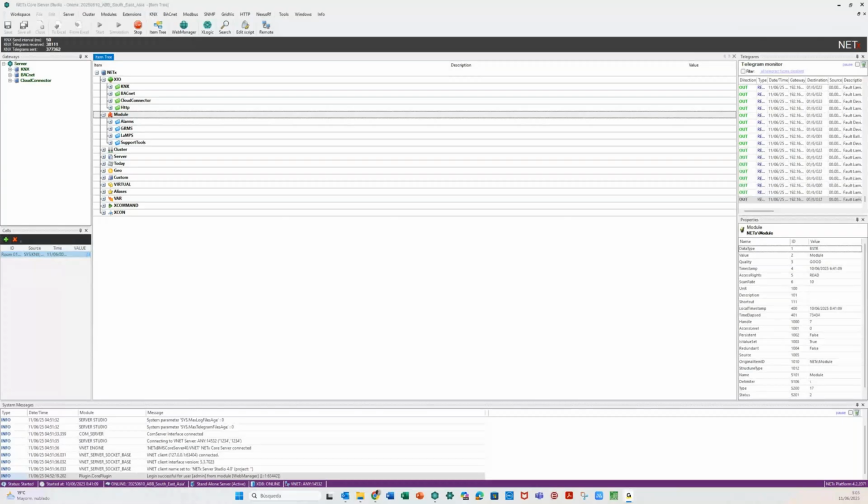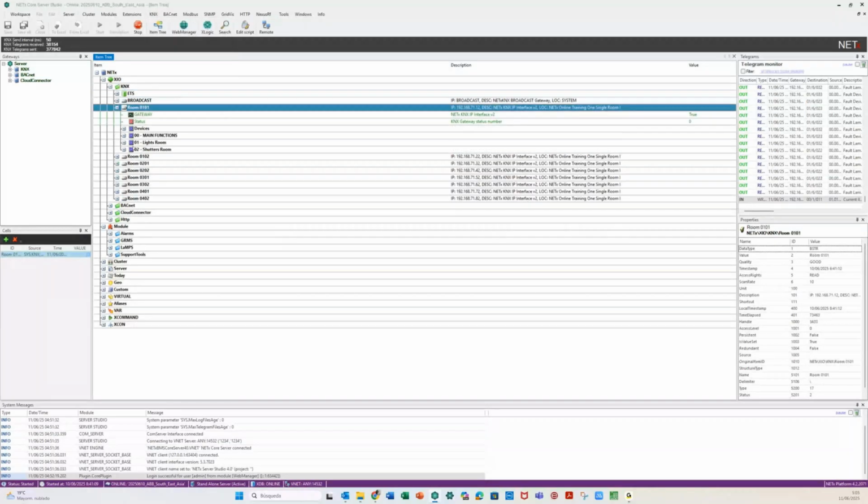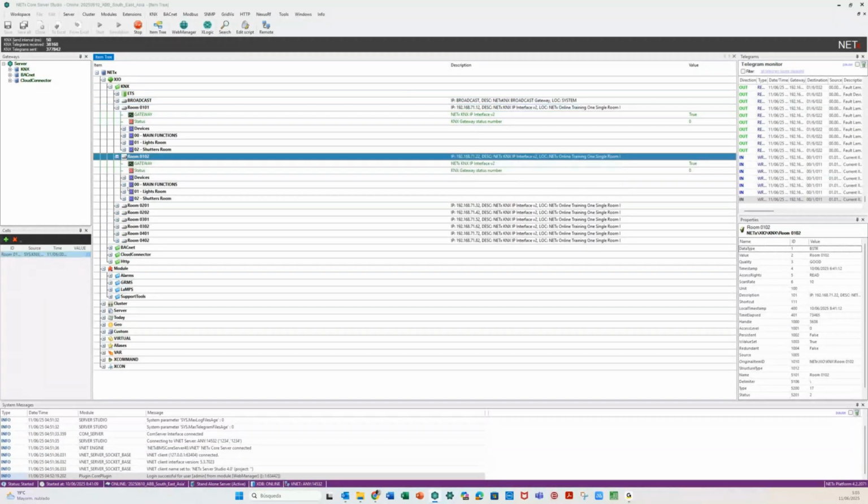Yesterday, if you remember, we started to integrate data points from different protocols and different technologies. So we did from KNX. As you may remember, we integrated this by importing some files from the ETS project we had. What we got at the end was the same structure in terms of data points, group addresses, and individual addresses for every single practical board. In this case, we have 8 practical boards from KNX with exactly the same configuration.